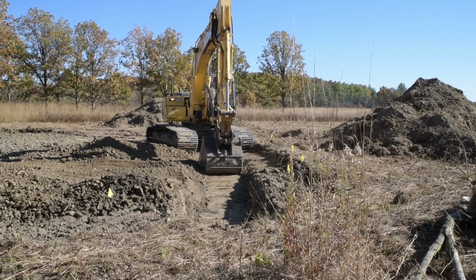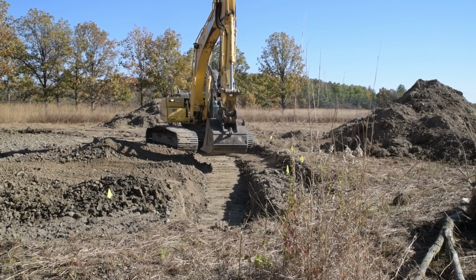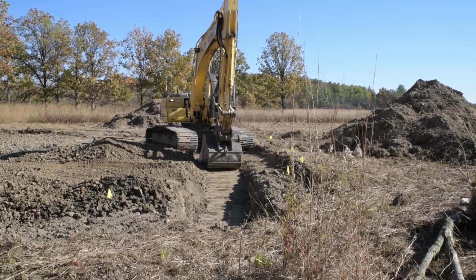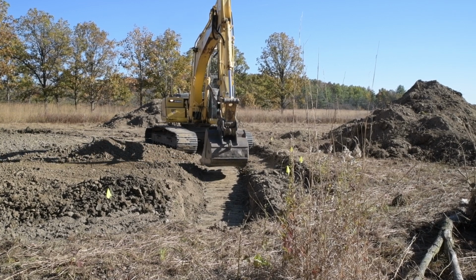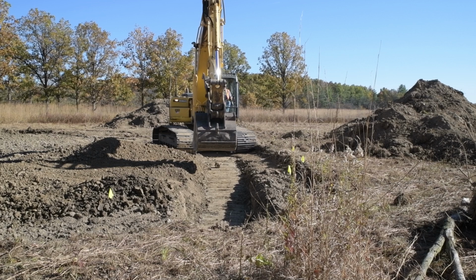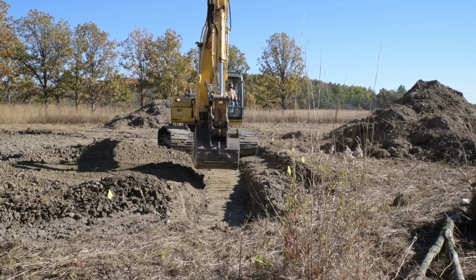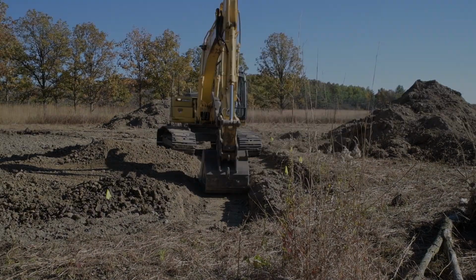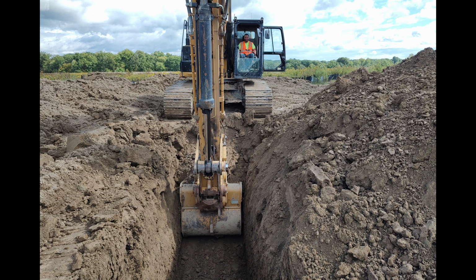The action of compacting soil with a bucket of the excavator involves repeatedly raising the bucket of the machine up and down and pushing it with force into the ground. This will shake, rattle, and jar both the machine and the operator and can eventually damage the excavator and possibly harm the operator. This is why I try to limit the length of groundwater dam that I ask an individual to build by using an excavator alone to less than 100 feet per day.